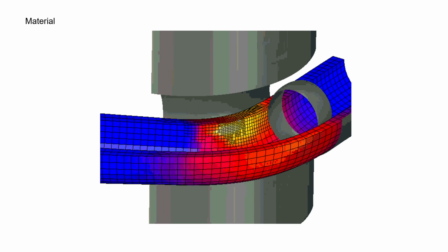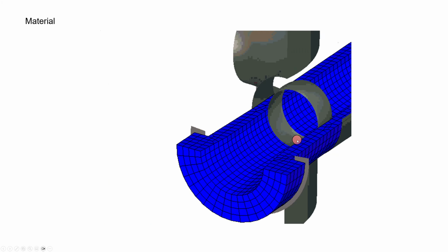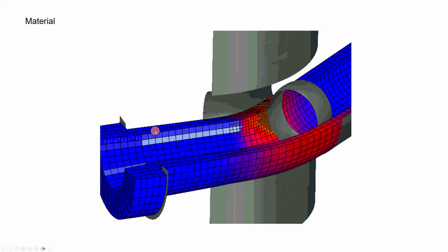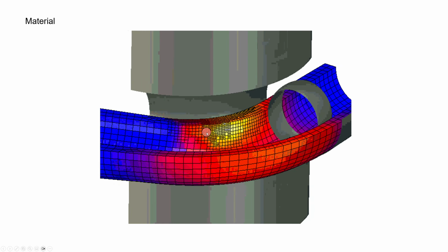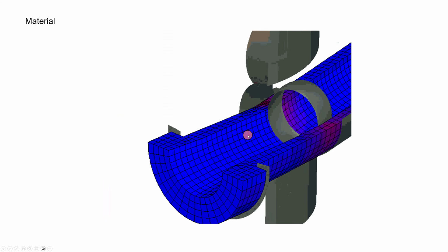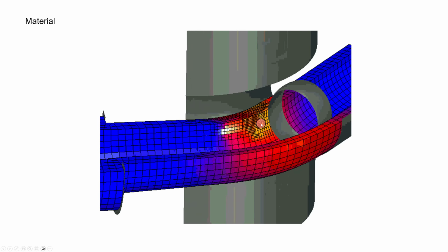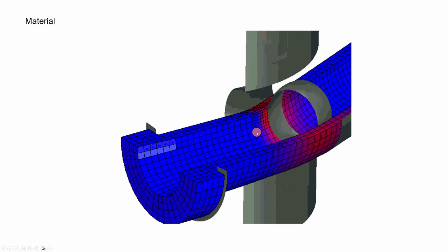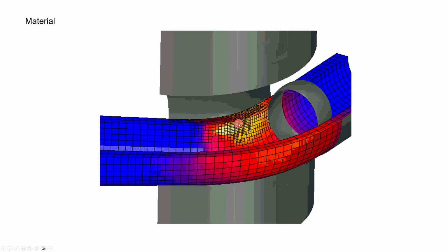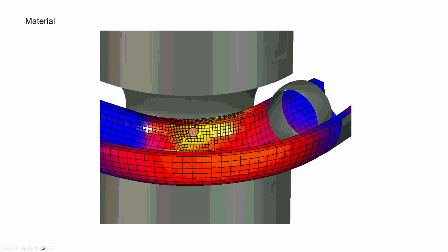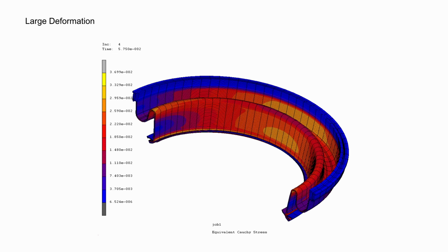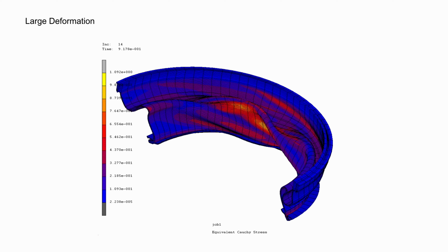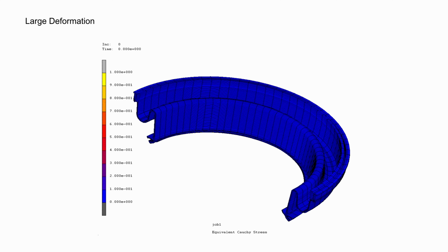While we're here, let me point out an interesting feature of Marc. You see how the mesh starts out as relatively coarse, but it's very fine here in these regions where we have a lot of complex deformation occurring. Marc is able to adaptively refine the mesh to give you the small elements that you need to resolve complex stress fields.